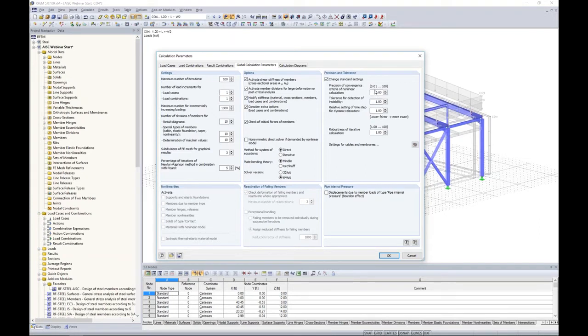The problem being, the lower factor we go here to get a more exact answer, the longer the solve time. And if you set this too high, then you might not have accurate results. So again, default is set at 1.0. Typically, you're not going to touch this. So that's why we have this grayed out as it is.